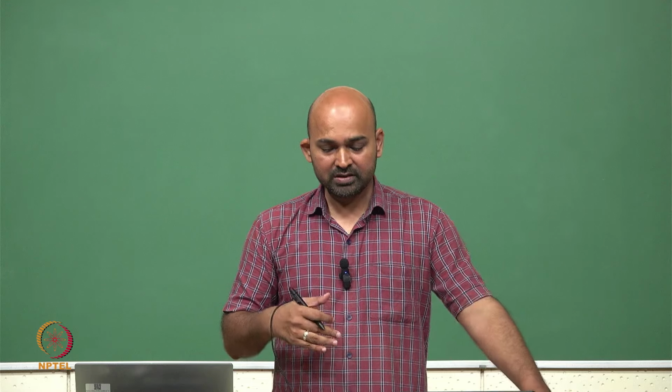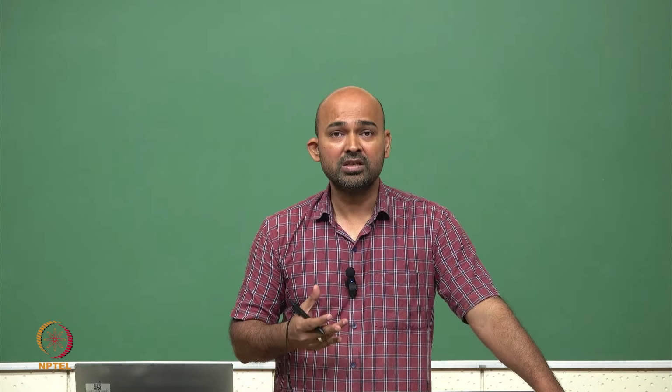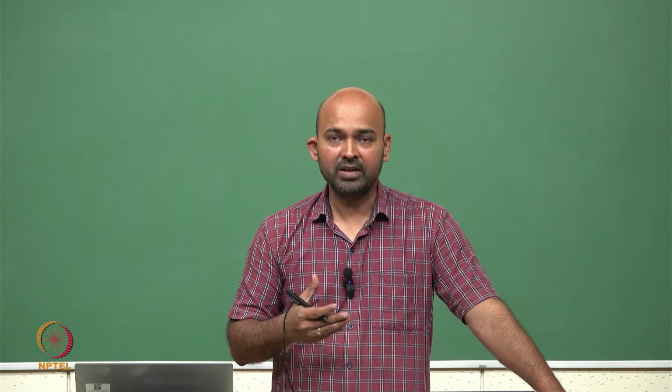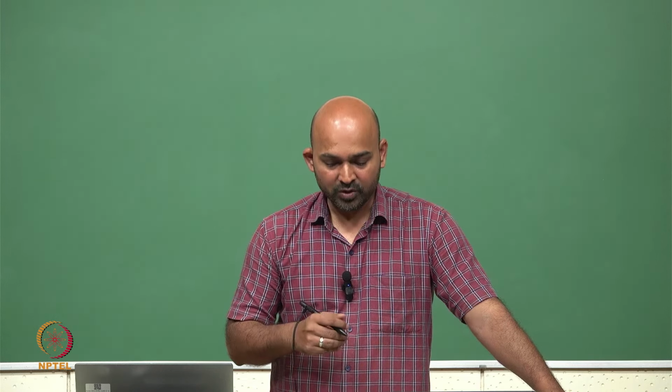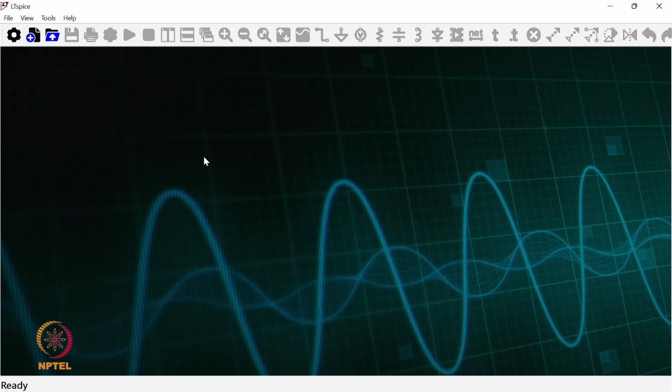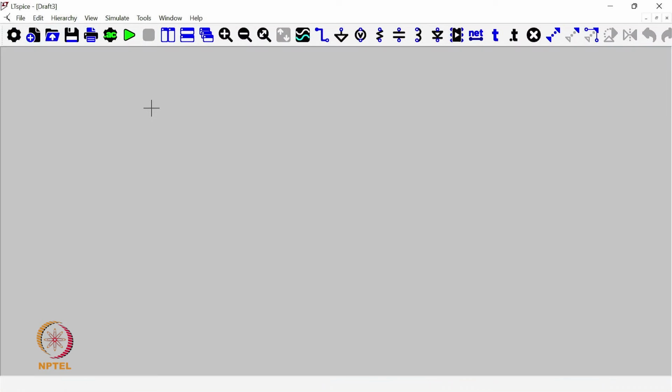Now, next let us discuss the transient simulations. How do we perform these kinds of transient simulations in LTspice? So, we go to the LTspice software. We open LTspice, which looks like this. We go to new schematic and then we make a very simple circuit.